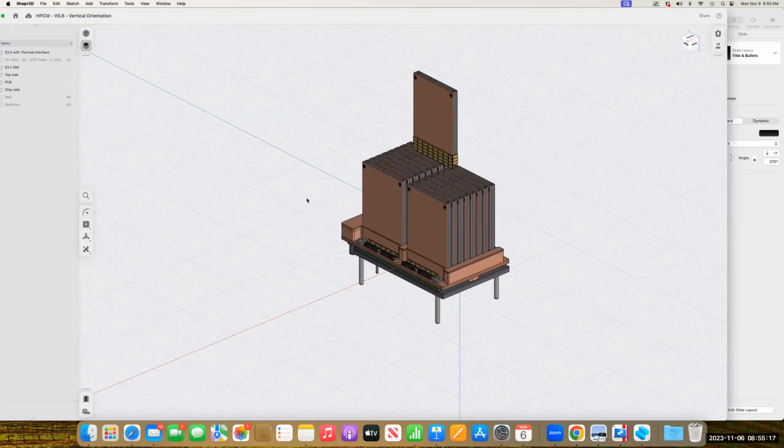Yeah, I think so. Still, one thing that needs to be looked into is how those frames support the card. The card is pretty heavy. So during the shock vibration test, that's accelerating to 50 G. Those forces need to be supported for the card. So some of those board locks are there for that purpose, right?